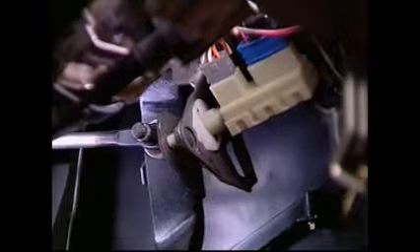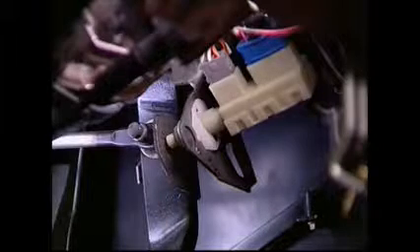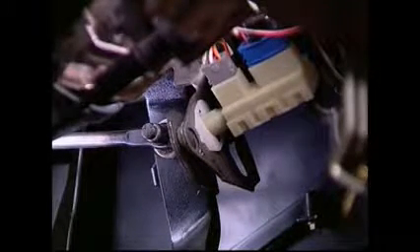The typical stop lamp switch is a normally open switch. That means that when the brake pedal is at rest, the switch plunger is pushed in and the circuit is open. No current flows through the switch to the rear brake lamps. As the brake pedal is depressed, the plunger extends by spring pressure to close a set of contacts inside the switch. The contacts close the circuit and allow current to flow to the tail lamps and the center high mounted stop lamp where the brake lamps are illuminated.